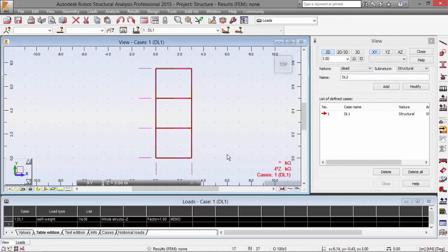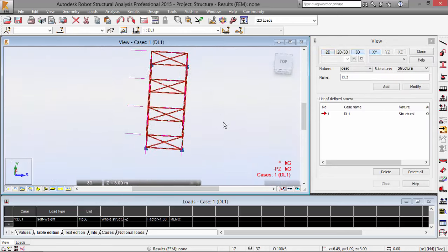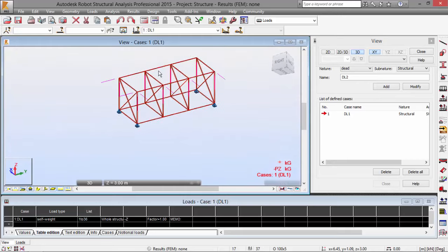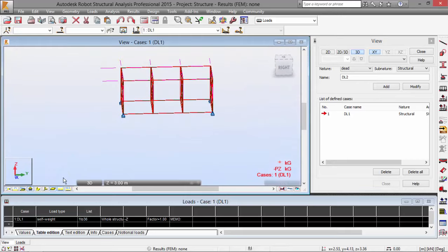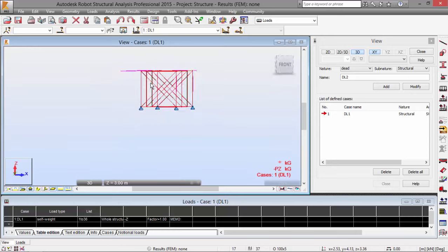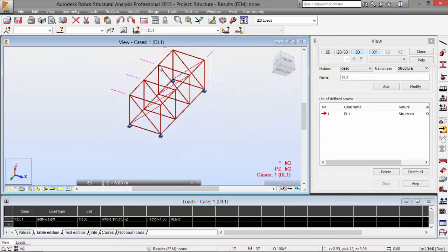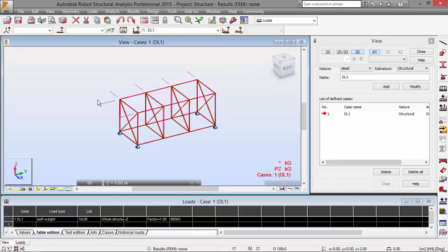As you may see, there we go, translational degrees of freedom. If I show this, these are just masses, so you don't get the value. You need to run a modal analysis or a dynamic analysis to see how this turns into forces.